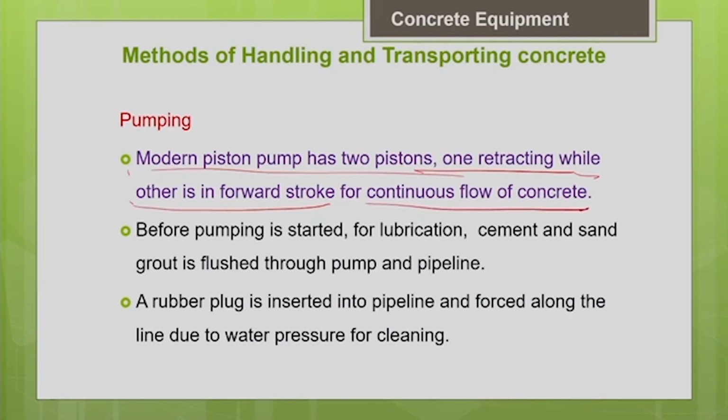Another important thing to be noted with respect to pumping: pumping is a relatively tedious operation, because before you pump your actual concrete mix, you have to do some lubricating or buttering job, as I told you earlier for the conventional drum mixers. Otherwise, if you don't do the lubricating process, in your first batch of concrete pumped through the pipeline, most of the paste will stick to the sides of the pipeline, and the concrete delivered out will have less paste and more aggregate. So that batch has to be thrown out.